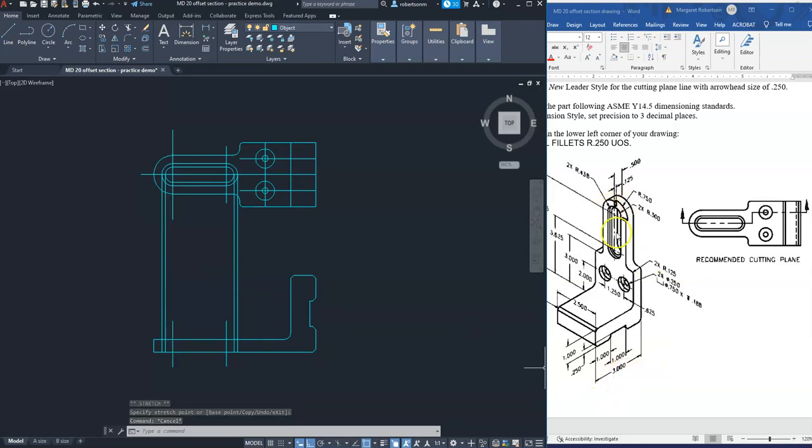Okay, this slot is 1/8 of an inch deep. It's 0.125, and then the smaller slot goes all the way through. So let's get an offset command, O for offset. The offset distance is 0.125, enter. We're going to click, oh, what is happening? I did something stupid there. Yeah, well, that's not unusual. So there's an O for offset. I'm going to now come down here,